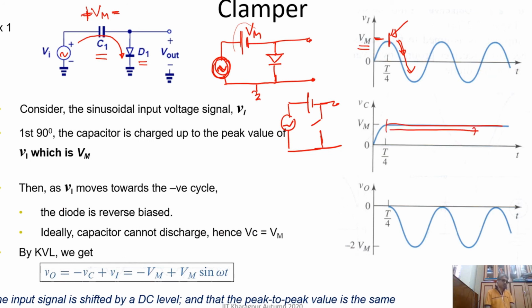If this diode is an open circuit, this input voltage will be across the diode. Now if you measure Vout here, you will get this Vi plus this Vm. But look at the Vm polarity, it is opposite to the polarity in which we are measuring Vout, right? So what will happen?